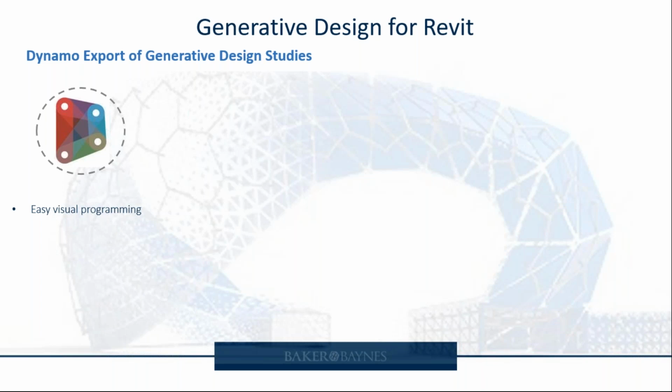It is a set of customized actions that help you to automate specific tasks. The generative design package is one of them. So you just download it straight from the interface, and this is what will allow you to push your scripts from Dynamo into Revit's generative design tool, where you create the case studies.